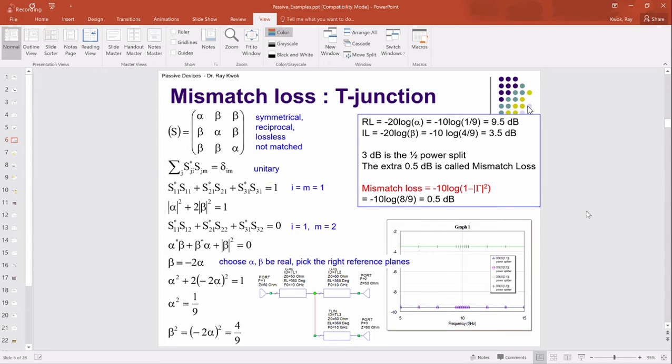Okay. So we could hypothetically make them match then, right? You can hypothetically make this 100 ohms, 100 ohms. Correct. Then it will be matched, but only matched to this port. Looking at this port now, this port is 100 ohms, looking at 50 ohms and 100 ohms. And they're in parallel, I see. Okay, thanks.